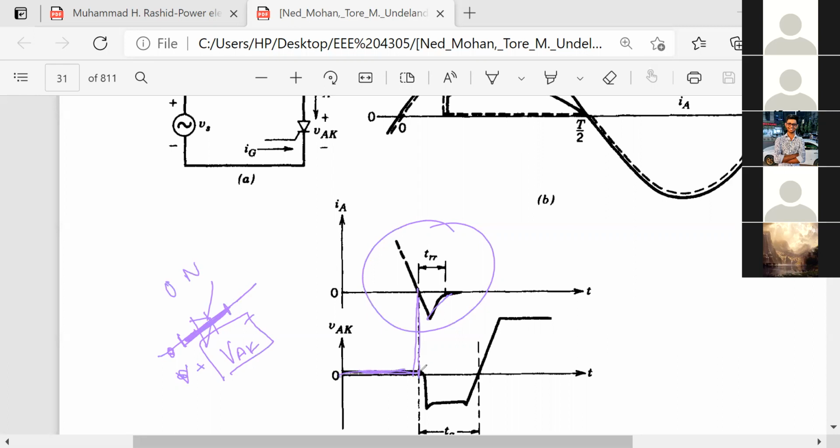Look here. Now they have given a reverse bias voltage or something like that. So still this is going to 0, and it should actually be the applied voltage, right? But during this TRR, it has a reverse voltage and then it goes to 0, and only then is the device said to be turned off, but still it takes some time to get the full recovery voltage.